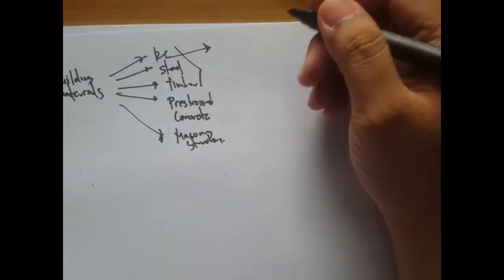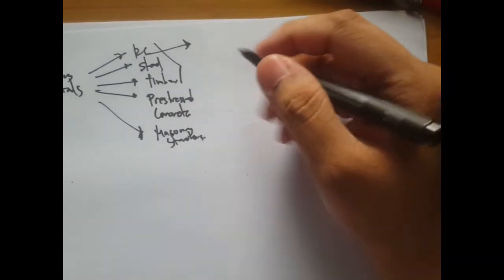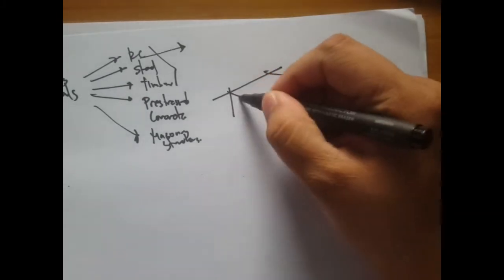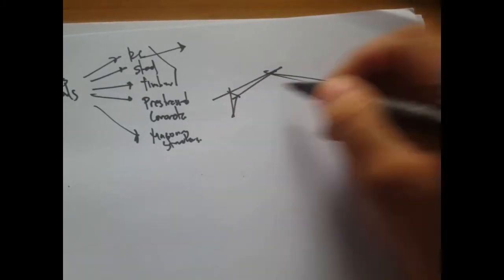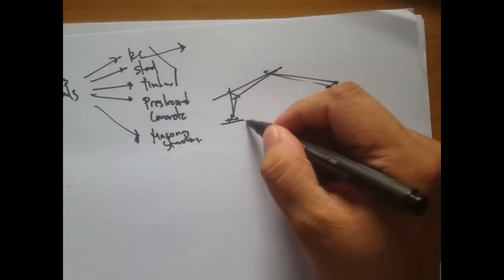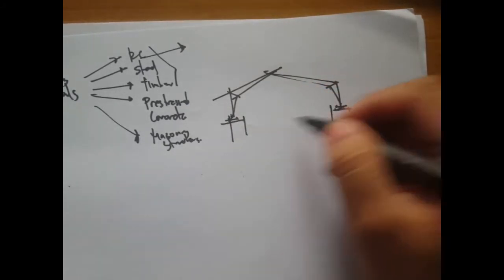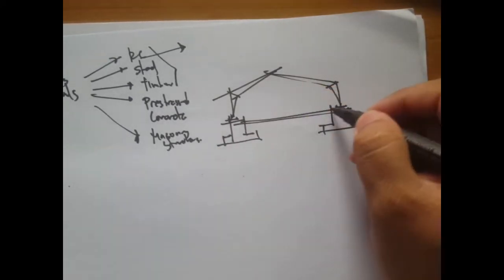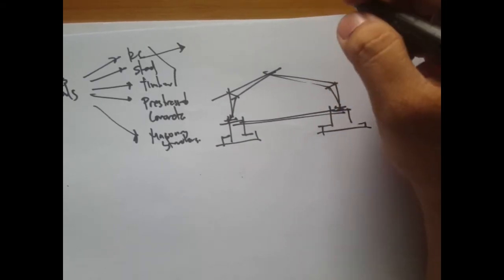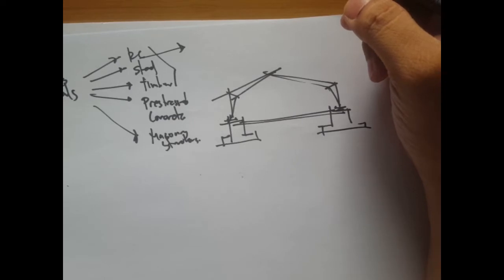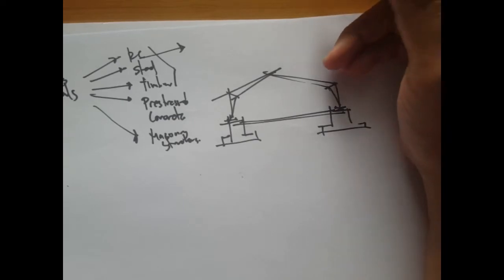Okay, so it's used in building foundations. You can actually find this even in steel structures, let's say portal frames. Even though the structure is steel, the foundation is built using reinforced concrete. So why is that? You'll notice the characteristic of reinforced concrete is its resistance to environmental degradation compared to steel.